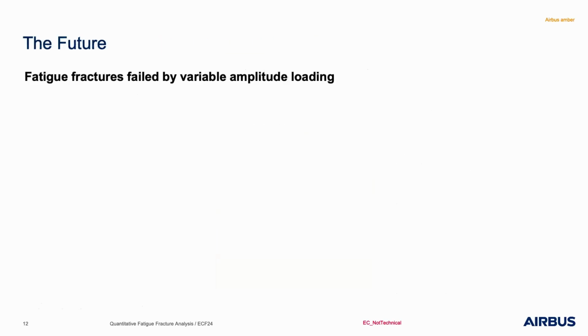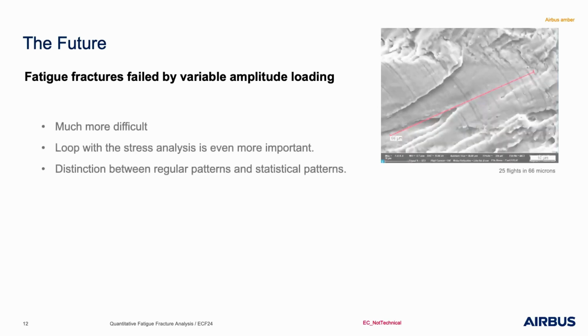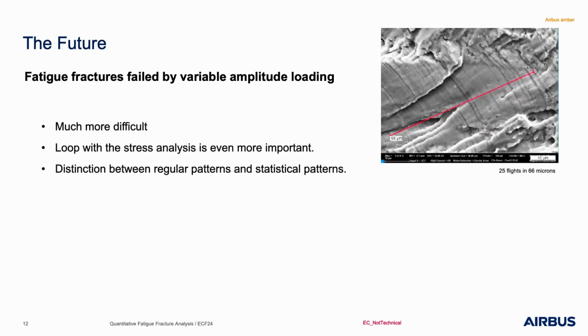And the future. Yes, that's what I have not mentioned up to now, is the variable amplitude loading, which covers 50%, to be honest. It is really much more difficult than the constant amplitude load. And here the closed loop of the stress analysis is even more important. And you can here distinguish also between regular patterns and statistical patterns.